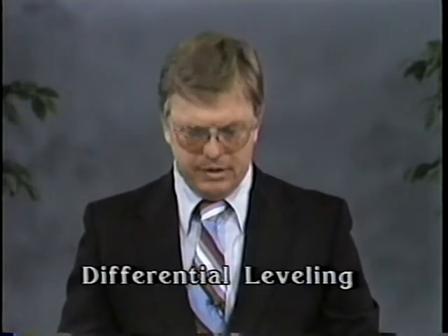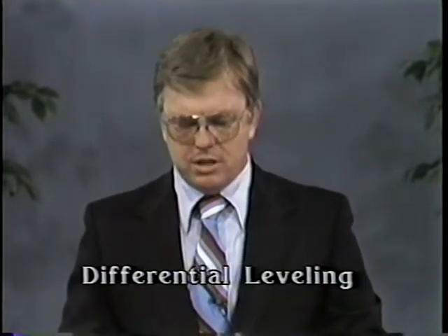Our third method of vertical measurement leveling is differential leveling. Differential leveling is a process of measuring the differences, the differentials, in elevation between any 2 points by spirit leveling. Differential leveling is broken down into different levels of accuracies known as orders. These orders are first, second, and third order. In first and second order, the orders are further broken down into class 1 and 2. The highest order of accuracy being first order, class 1, and the least accurate being third order. We will present a more detailed discussion of these accuracies later on.